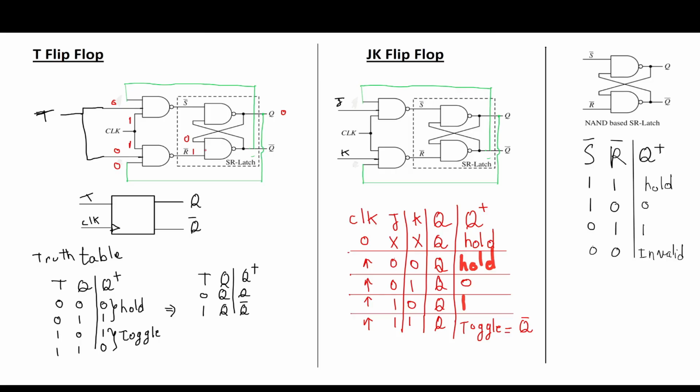Now from this NAND gate, we have 0 and 1. So also the output will be 1. So this Q bar will go in two places, but we're only interested in the upper left 3-input NAND gate. So this one will become an input to this NAND gate. So this top NAND gate, we have 2 1s and 0. So the output will be 1.